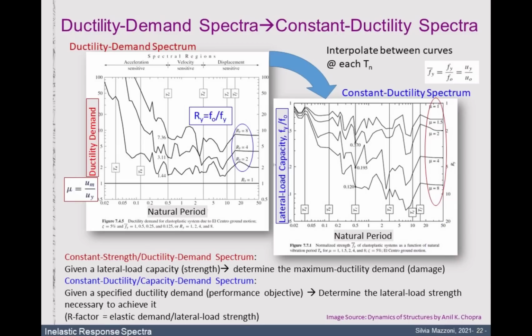And so it's very important when we're looking at inelastic structures to make sure at the design end to provide that ductility capacity. So the ductility level is really important in what we're doing, and we're computing our inelastic spectra, because that's what we're trying to communicate to the designer or to our client. The inverse of that is, and this is almost the most popular spectra, the constant ductility spectra.